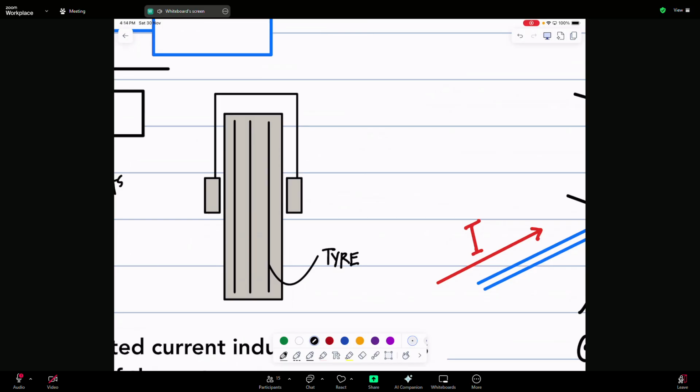what? Friction. And that car braking, right, all that kinetic energy, it's insane amounts of KE. If you just do a simple math, your car going at 100 kilometers per hour, right, it's almost 500,000 joules of KE. Where does that go when a car brakes? Heat, just pure heat, and it's wasted.